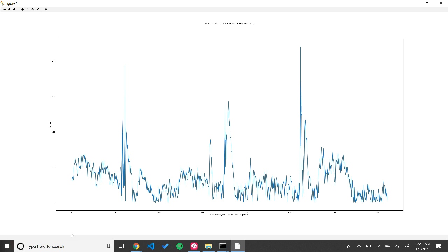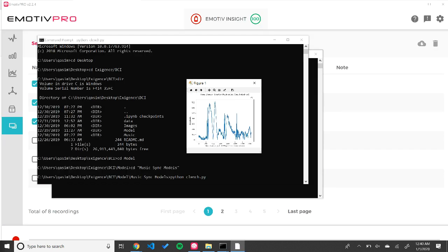So this is data in the time domain, and I would just have to perform a DFT, Fourier analysis, and you could do that using a fast Fourier transformation to convert it all into the frequency domain. The window that I would use would be a regular Hamming window.